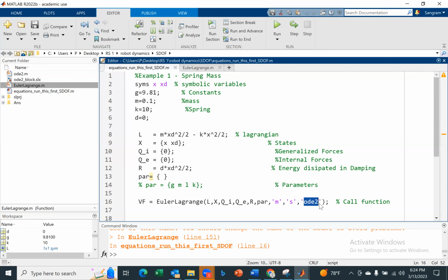Yes, if we have a robot with a damper, then we will add some damping coefficient. But right now, in this particular problem, we don't have a damper, so we are ignoring it. If you want to run this code in the next iteration, D here I specified as 0. You can specify the value of D as 0.1 or 0.2, and you will see the response of the system. Everyone understood so far? Okay.